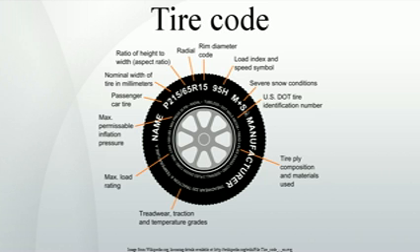All tires for use in the USA have the DOT code, as required by the Department of Transportation, DOT. It specifies the company, factory, mold, batch, and date of production: 2 digits for week of the year plus 2 digits for year, or 2 digits for week of the year plus 1 digit for year for tires made prior to 2000. Although not law, some tire manufacturers do not. Tire manufactured in 10th week of 2001.